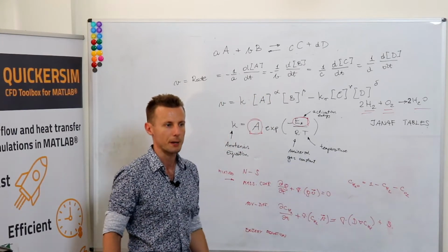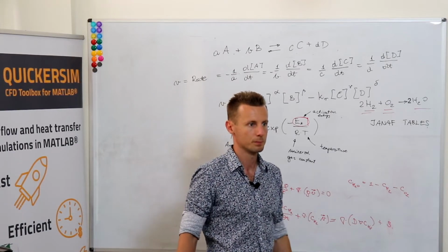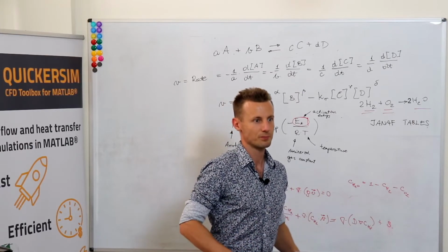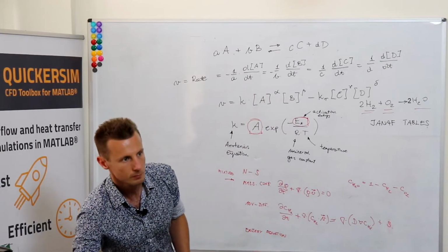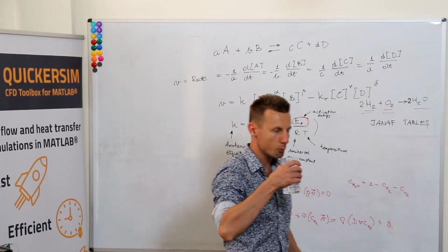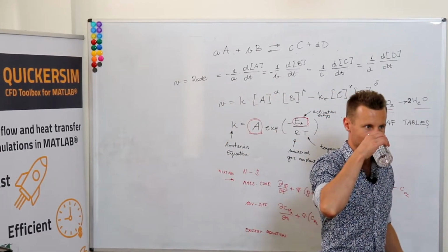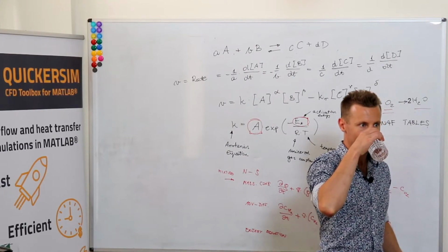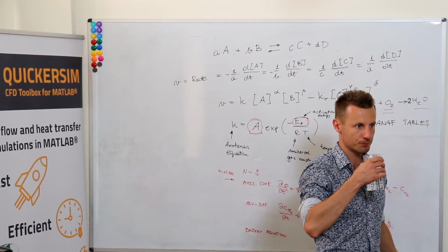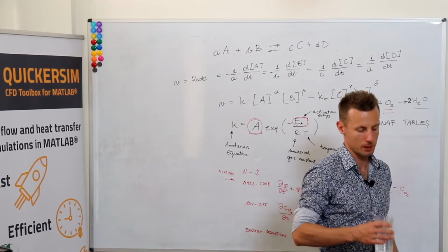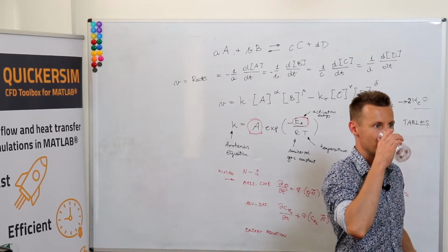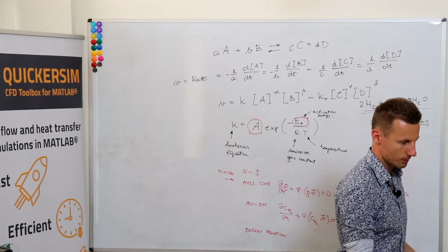And also a practical note, because Konrad and I stumbled upon this problem once upon a time. The material which is used as the completion to one, the nth material, is not chosen by hand in a program like Fluent, for example, but when you're defining a mixture, I believe it's the last component you define. You can very easily fall into a problem where the last material you defined was, for example, the oxidizer.